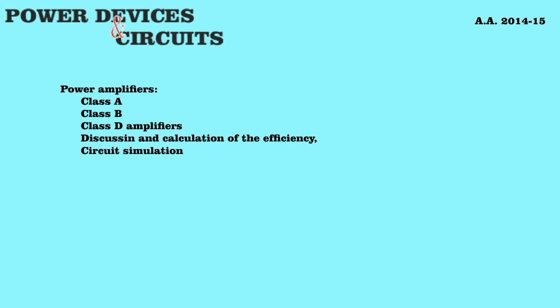This will work. However, we will discuss this later. This only works if the modulating frequency is much higher than the signal frequency. You want to have many pulses that will construct your input signal again. This is a very simple example of a Class D amplifier.